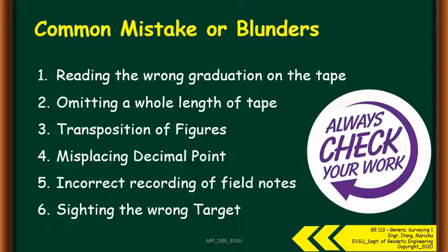Misplacing decimal point. Example kanina, instead of 100.0 centimeter, yung sinulat mo is 10.00 centimeter. So, malaking difference. Incorrect recording of the field notes. That's why if you record your data, always check your data. Citing the wrong target is one of the common mistakes.